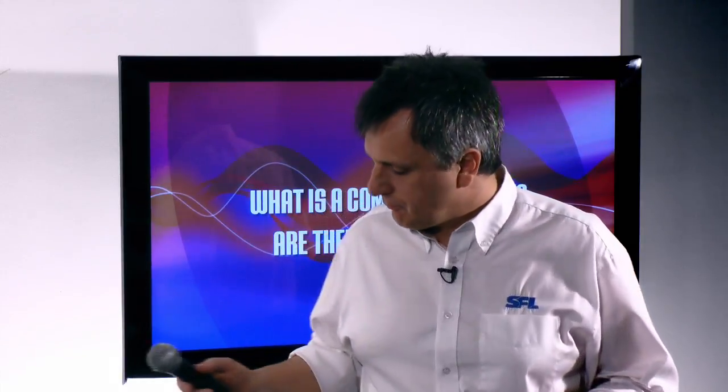I hope this has proved a useful introduction to why we compress and how we compress. One of the things I wanted to say is that the control of level is so important when we're mixing live sound. Compression is going to be inserted on every channel, and it is the primary way in which we mix volume. Once a sound engineer starts working with multiple channels of compression, we almost stop touching the faders, and we start to balance the volume levels by the exact tuning of the threshold positions.